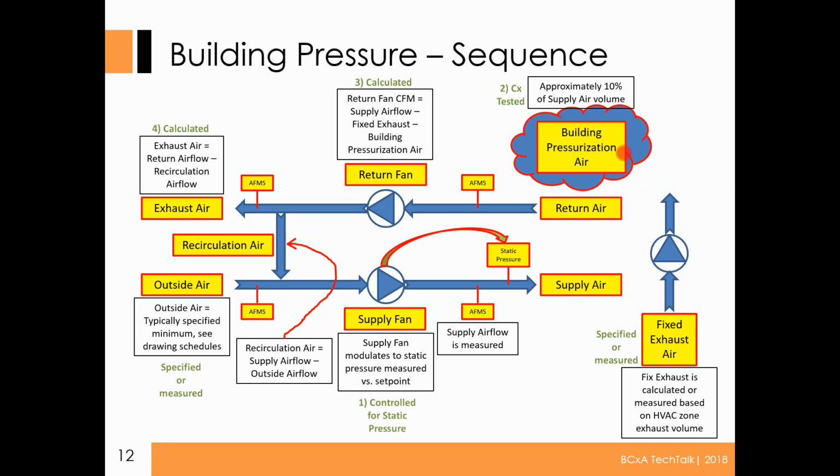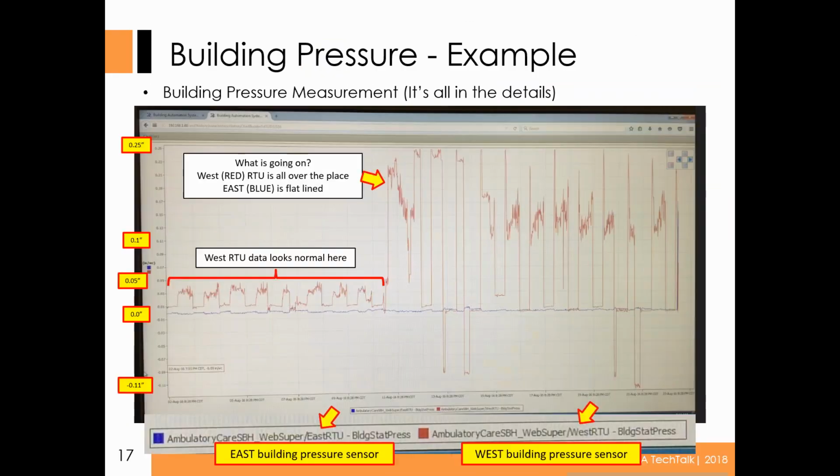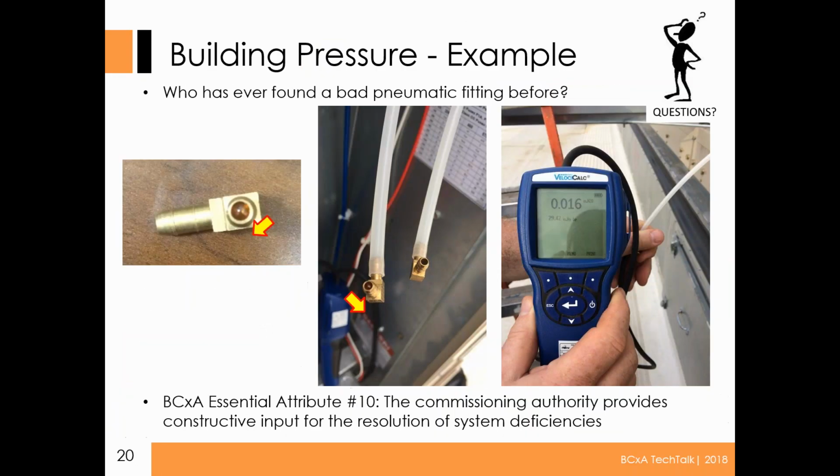Okay, and we have had a few other comments that came in, but I'm going to send those to you after, and maybe we can have a little follow-up. But I wanted to get to a couple other questions that came in. This one relates to slide 21, I believe: did you drive the duct static by opening the respective VAV boxes or just increase the duct static pressure set point?